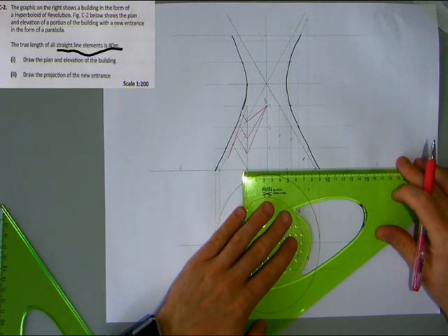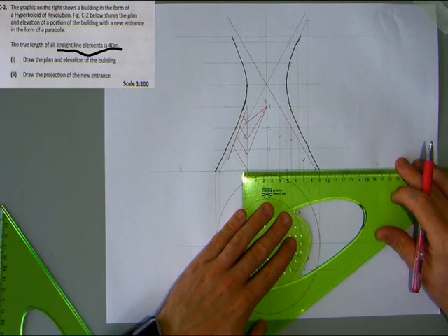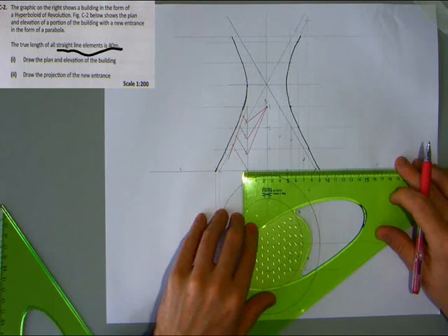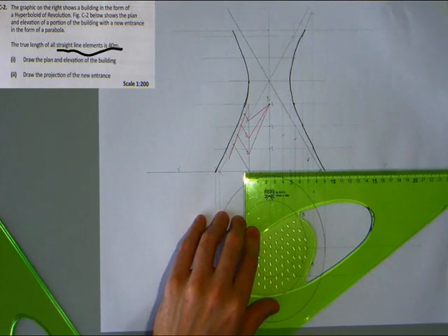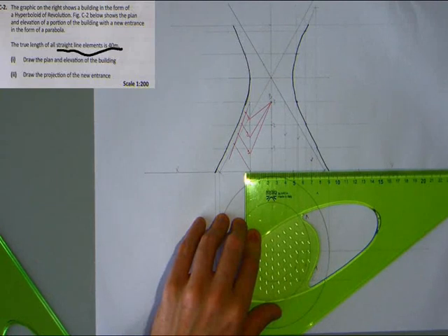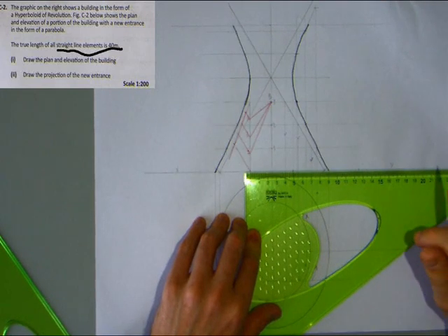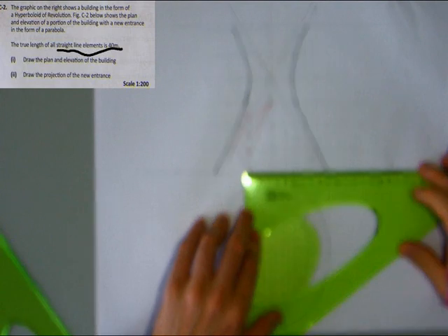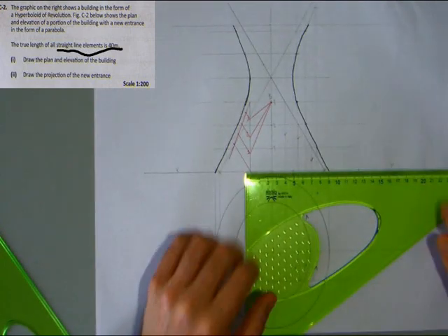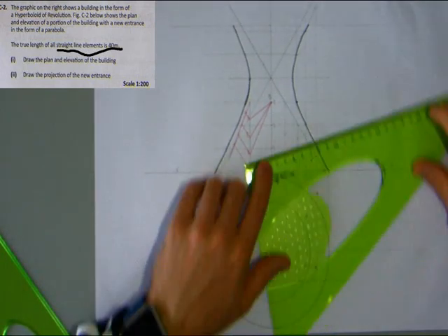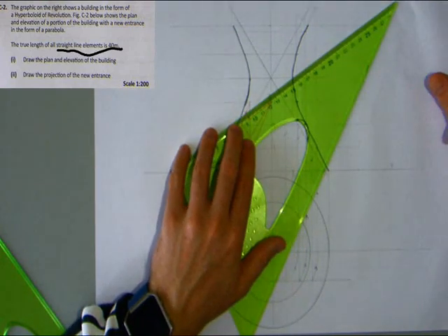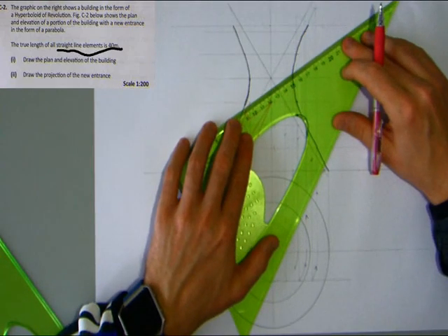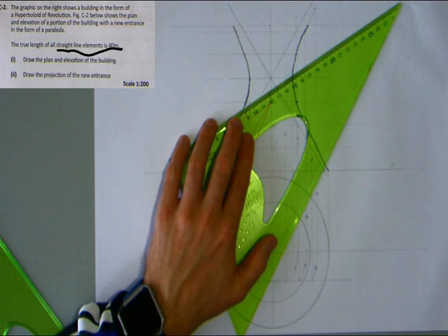Okay, we don't know the measurement of this line. It's 25. 25 divided by 4 is actually quite difficult. I'm just going to zoom in here a little bit more, give you a better idea. Okay, so 25 is actually difficult to divide by 4, so what we're going to have to do is use the divisional lines method again. Now, at the top part of this we're finished, so I'm going to use a green pencil here.